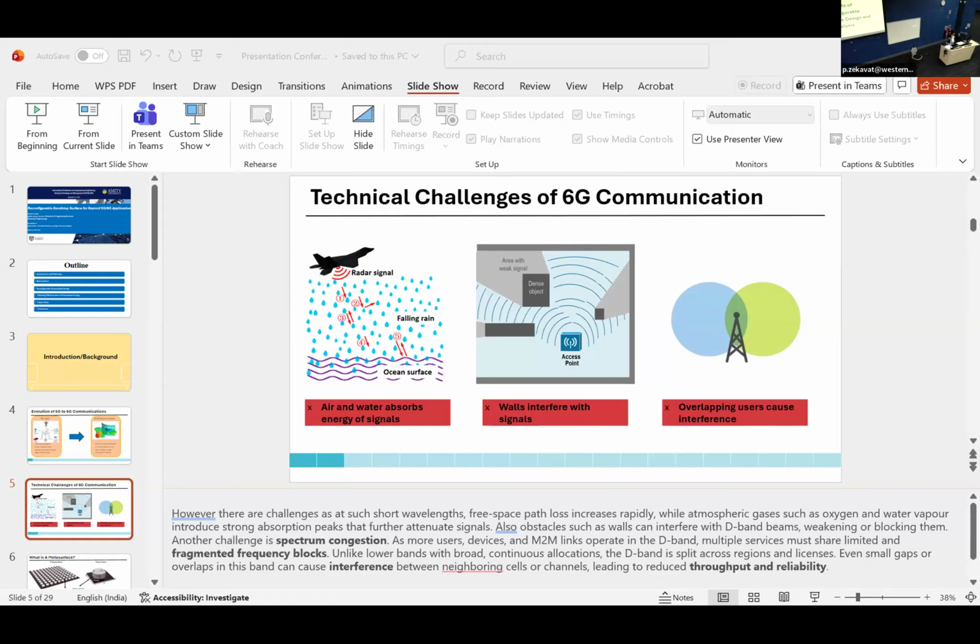So looking at the results of sweeping the D-band frequency for the different diode states, these figures present the S parameter results for the metasurface operating in transverse magnetic normal mode. Starting with all diodes off, a stop band was found at 156 gigahertz. A secondary stop band, a little bit weaker, was found at 126 gigahertz. And then the reflection coefficients found 0 decibels around these frequencies, further confirming the stop bands.